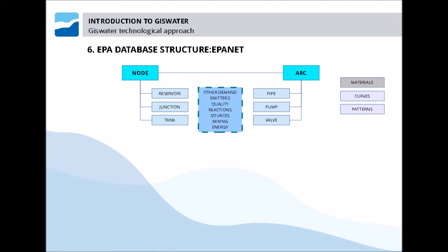Once we have created all the information, we are going to choose what sector we want to export from the model, because an important thing to mention at this point is that all the information of a network will be structured in sectors so that we can export one or several sectors to the mathematical model. This is going to ease the process for faster speed in the calculation, since it is never going to be necessary to export an entire network. We can simply export the sector that interests us.